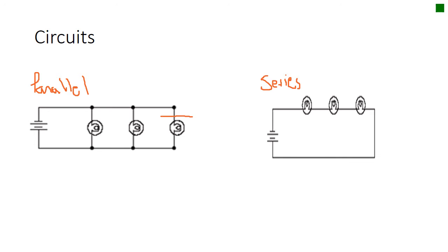Just think about it this way: if you're drinking chocolate milk in a cup or glass, I should say, and you use two straws, it's easier to drink out of two straws than it is one because there's less resistance. The voltage is going to be the same throughout the circuit, so the voltage of the battery is equal to the voltage drop across each load. Okay, so voltage drop, again, we measure here across one load, across another load, and that's used by a voltmeter. As you increase the number of loads placed in parallel, the amount of current drawn from the energy decreases.